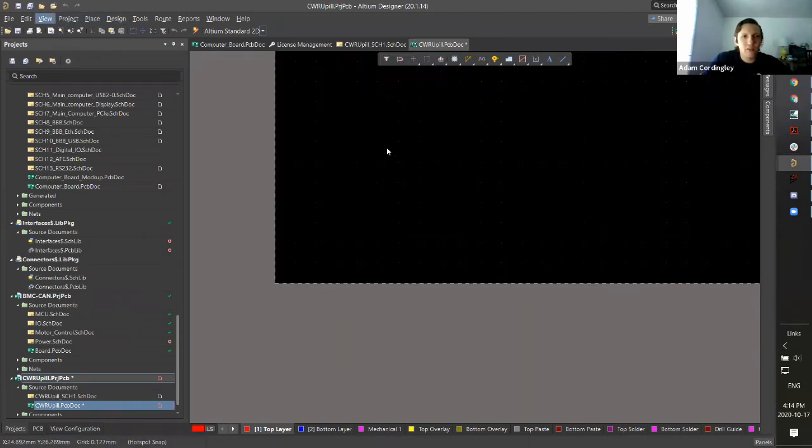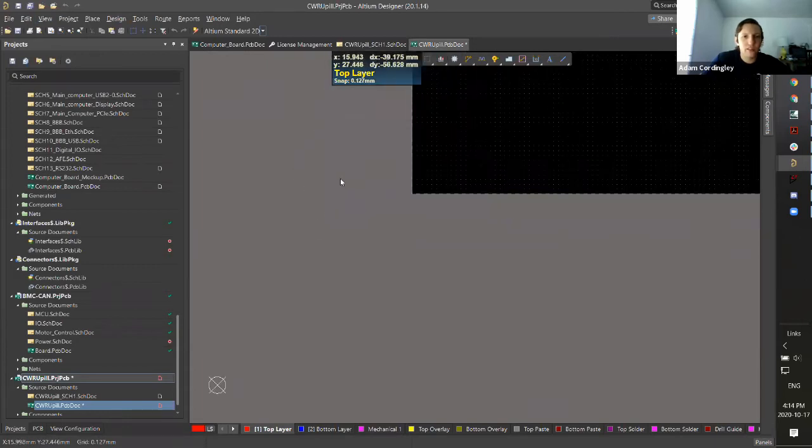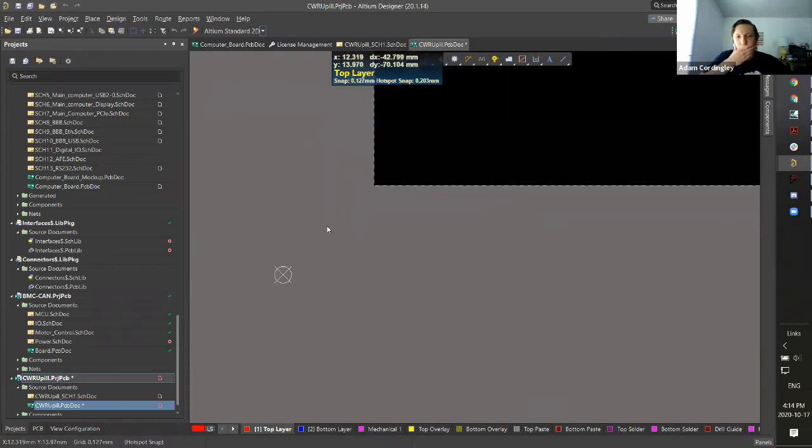And there's actually kind of a strange reason that I also do this, which is that components, you can't actually move them to the left or to the bottom of the original origin point. I don't understand that constraint whatsoever, but that is just a constraint of the software. For some reason, the component cannot be placed to the left or bottom of the original origin. I can prove it to you, and I don't understand why Altium is like that, but it is.